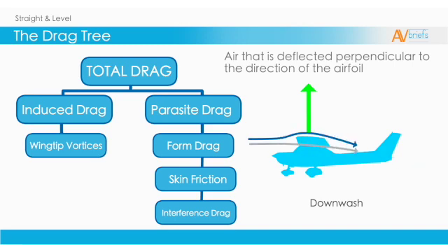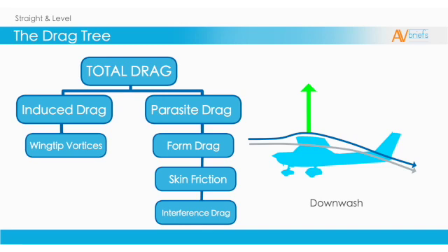Fun fact. As the actual airflow is being curved downwards at the rear, the actual relative airflow is considered to be curved downward as well. As lift is always perpendicular to the relative airflow, it is actually bent backwards towards the rear of the airplane. As it now has the effect of not just pulling upwards, but slightly backwards, it is producing some drag.